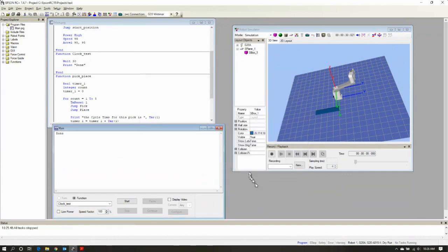One thing I will point out, since I've upgraded to Windows 10 and begun using it, I've not had to adjust those numbers. My clock has been very reliable for me, but you want to test it on your machine. Depending on what you have running in the background, it could be off. Now, once you make sure that your clock is synced, you're within that plus or minus 1 second, cycle time analysis running the simulator is going to be plus or minus 15% of the real world.